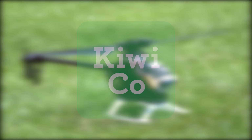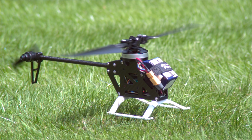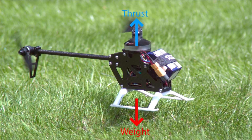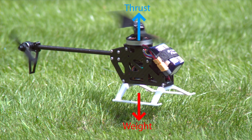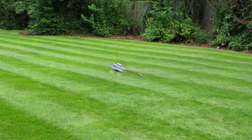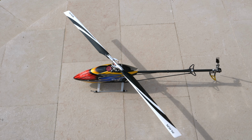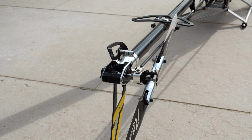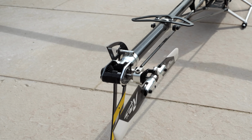For a helicopter to fly, there are 3 main requirements. The first is it must produce enough thrust to lift its own weight. The second is it must have some form of stability or control to keep itself level and prevent a crash. And the third is all the torque produced by the rotor must be counteracted either with a tail rotor or another rotor that spins in the opposite direction.